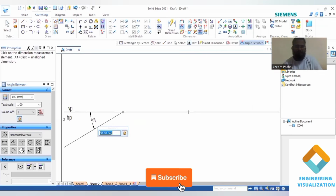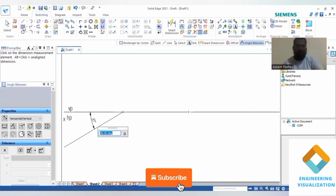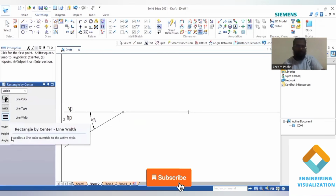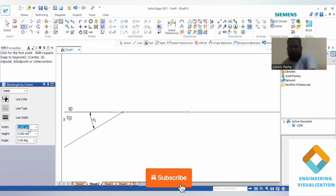Now you have to take the square of dimension 40 and place it with respect to that vertical edge. You can give the width and height the same, using the rectangle by center command, width 40 and height also 40. The angle you can give is 45 degree, so that it is easy for us.